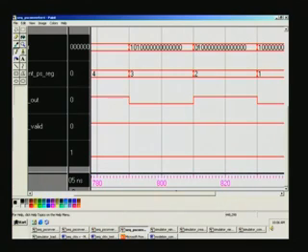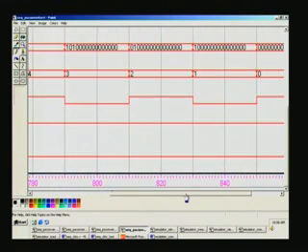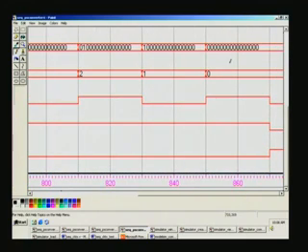Then again this one will go through to the MSB, and again you can see the data out toggling, and finally it lands up at 0 here, and we started with 0 1 0 1 and so on. So, the very last must be 1, because it is a left shift in 0 1 0 1 0 1. So, the last bit will be 1. So, after 16 shifts here, once again data valid goes low and end of conversion is activated here, and this completes the parallel to serial converter, and we will go on to the state machine.